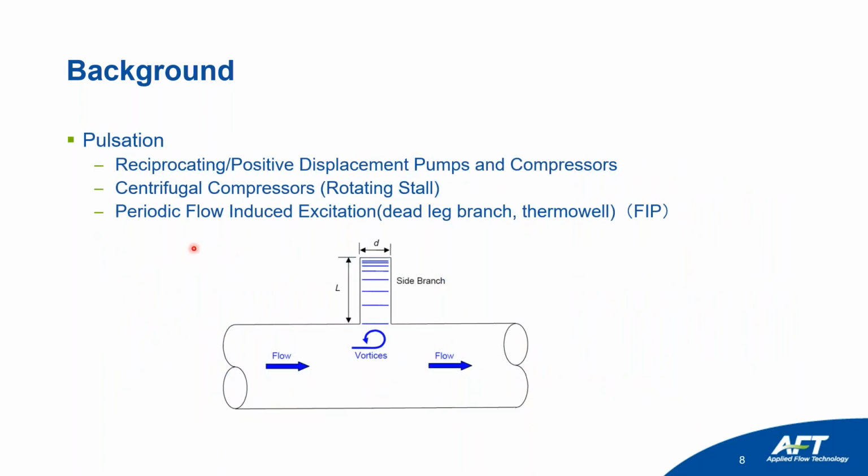Another source of vibration is pulsation. As we know, reciprocating and positive displacement pumps are a source of vibrations. So are typical compressors, when they turn into the rotating stall condition, and also periodic flow-induced vibration due to dead leg branch, thermal well, FIP.